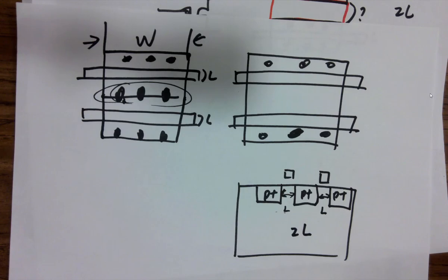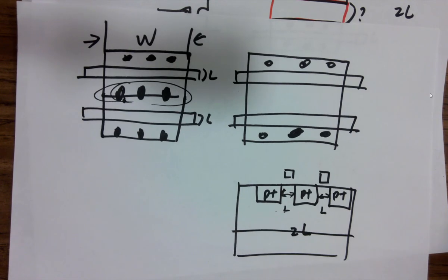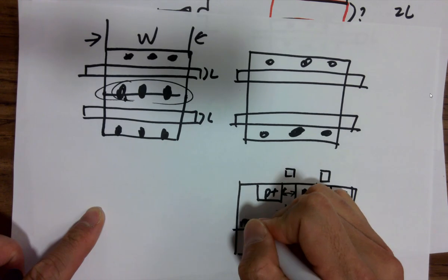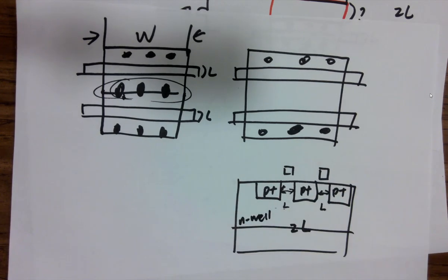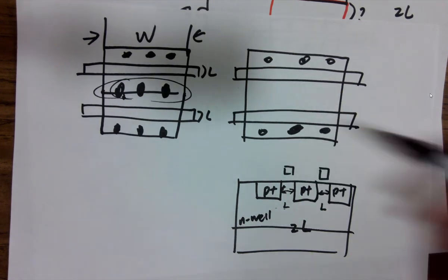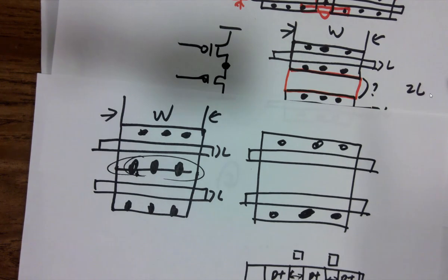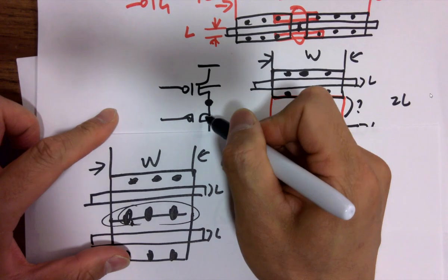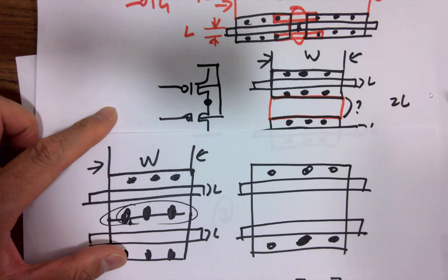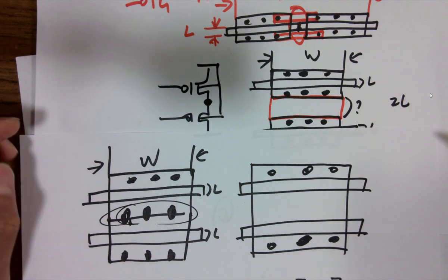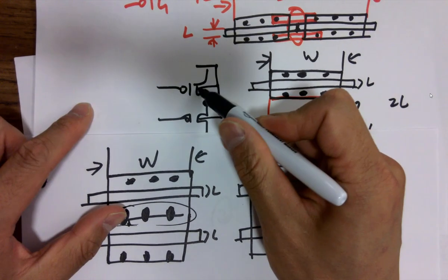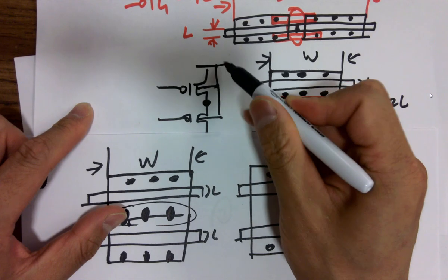And that's in an n-well? Yes, it has to be in the well. And there's the n-tap. We don't have n-tap. There's no n-tap based on this version. But if I draw this, then you need to draw n-tap because that's the body contact and shorted to VDD.